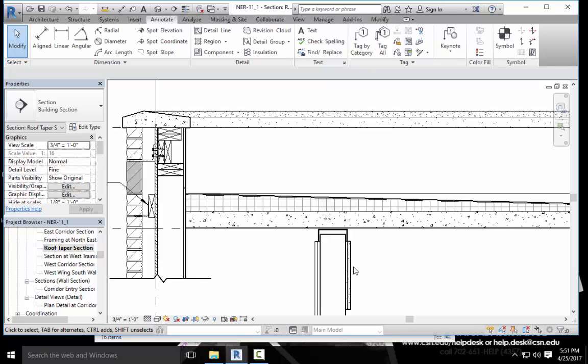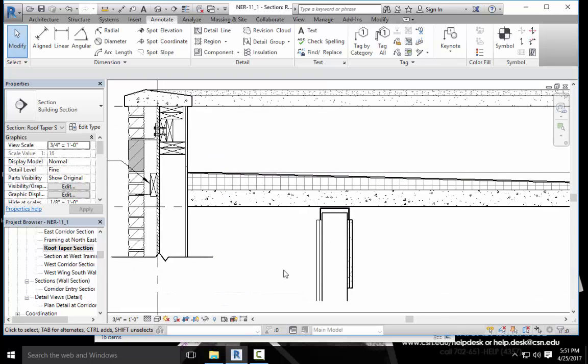Your detail should now look like figure 11.68. And for the most part it does. We have the chipboard drawn a little bit differently, but that'll be okay. Now you'll open the original group and make modifications to see how each insertion of a group is influenced. This is where the advantage of using a group in a model comes into play. When the modifications are completed, the other groups will be updated. In the project browser, find the typical wall termination view under drafting views.